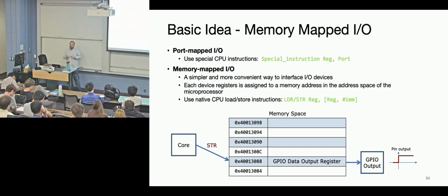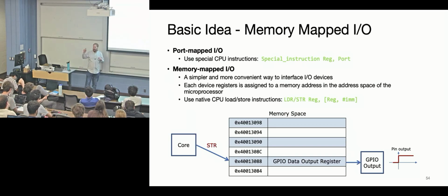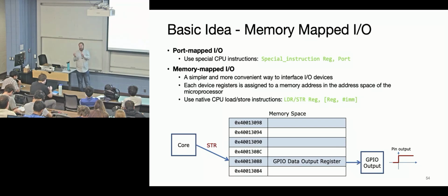But now you have to have a special instruction for every one of these functions. It's faster, or it could be faster, especially if it's something complicated. You could have an instruction that says enable port A, output, pin 1, output high, right? That would save you multiple loads to do that instruction. However, it's very specific and not generalizable. So ARM has gone with, let's make generalizable instructions.